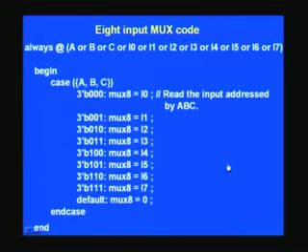So what you have seen earlier is a mux circuit, and this you are already familiar with. It is an always block with a begin here and end here, and now we have added one more statement called case here, which is very close to the C case, except that this is actually hardware design, which you should bear in mind. We have also seen a concatenation of 3 numbers here, and that is how we put them within brackets. This also is a mandatory thing.